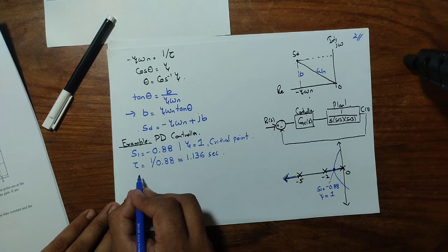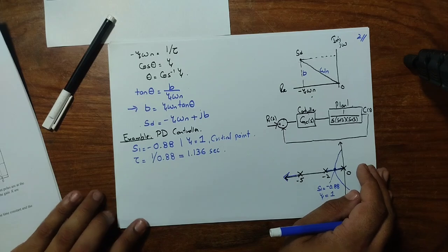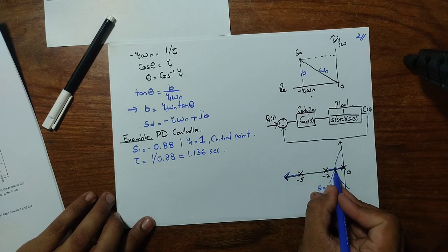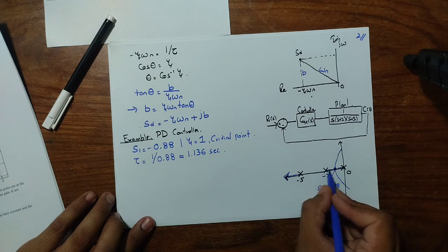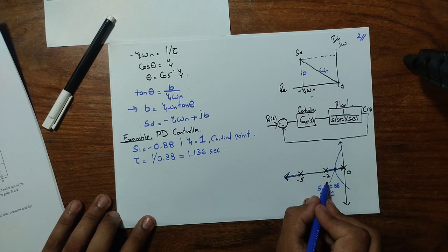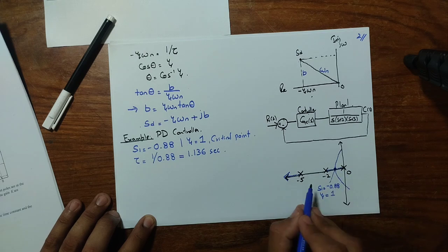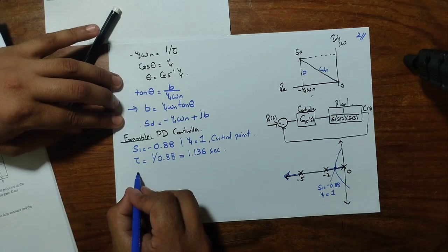Similarly, following the earlier method of the root locus, we can find the magnitude of the gain k that the system needs to reach this critical point, meaning how the poles will reach this point. There is no zero in this system, so we can just calculate the vector lengths from each pole to this point.